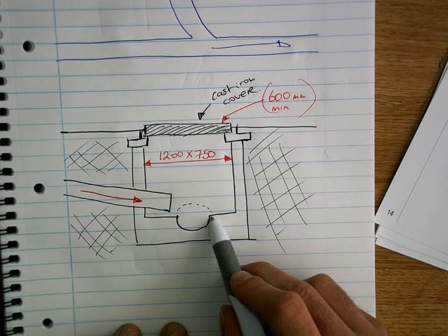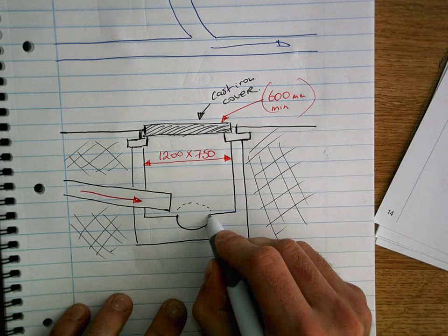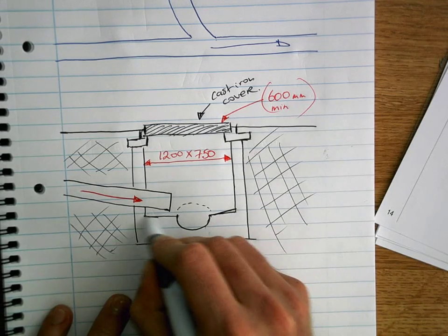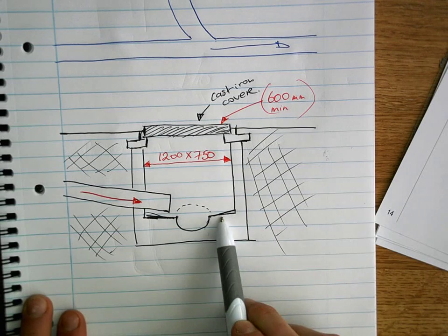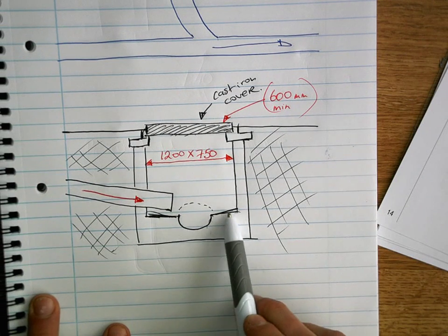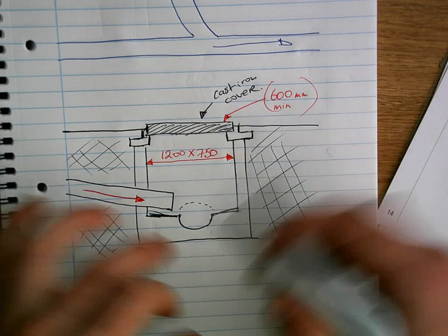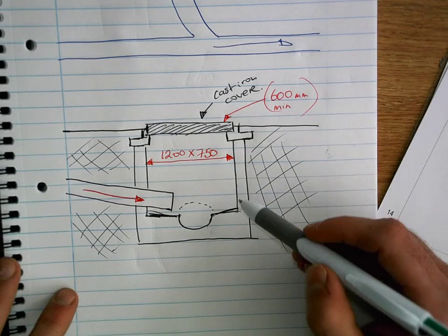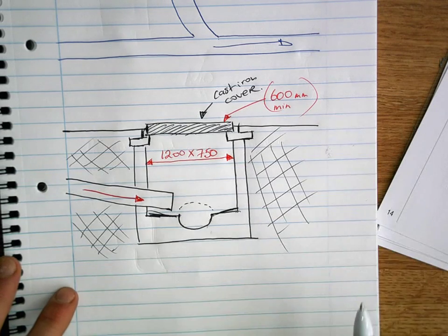Now the bottom section here, just make sure that it's obvious that that will be slightly sloped to actually run into the mains pipe, because when you have wastewater coming down here, you don't want it to build up in these kind of sections here. It makes it impossible to work in that manhole. So they will be sloped, so if any wastewater came down or other type of waste, it's going to flow down into the main sewer pipe and then flow on from there.